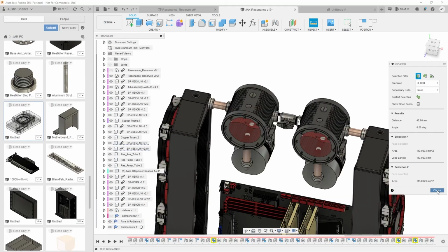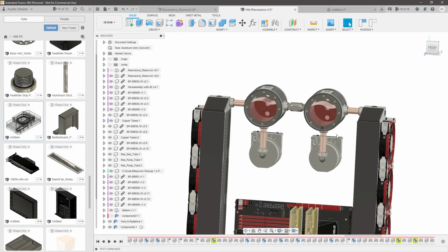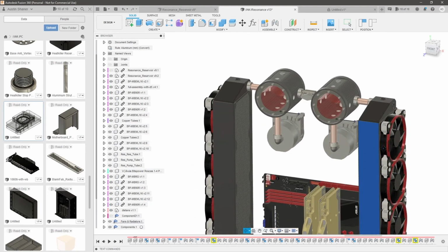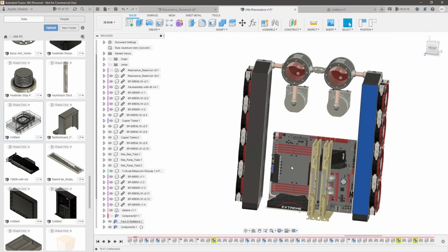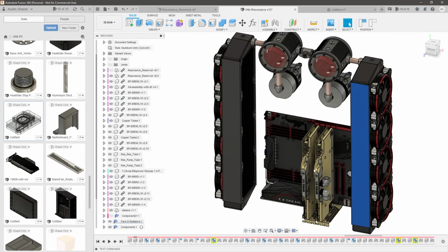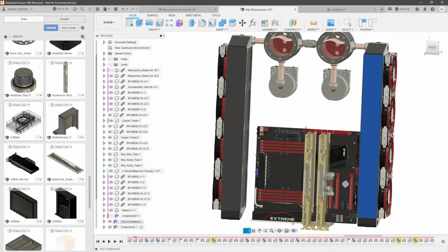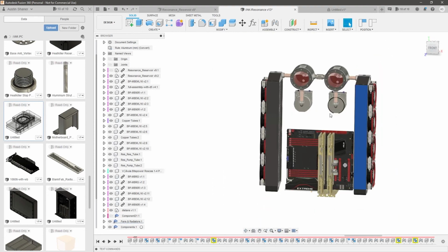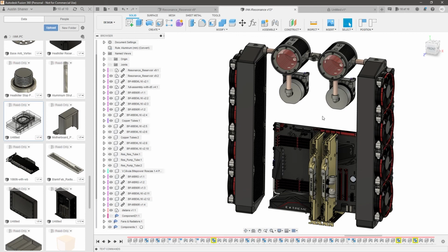So bringing up my previous design, you can kind of see what I ended up doing here. I didn't have the copper pipe between, but I had the valve. But I inserted these subassemblies of the fans and the radiators, and I inserted the subassembly of these two, and I inserted the pumps and the motherboard, which is a subassembly with all the various components, and the graphics cards, which is a subassembly with its various components. And then in this file, I could start creating piping linking between all the different components based on where they were joined or mated to. And so that was a really interesting way of doing both a bottom up and a top down, because I did bottom up by bringing in the separate part files, but I also did top down by drawing in components that were exclusive to the context of that assembly.